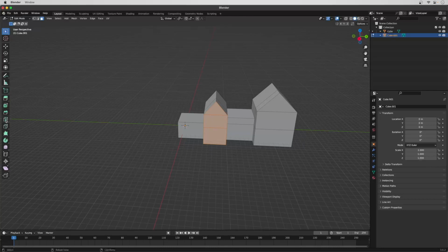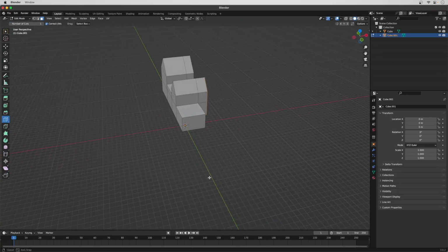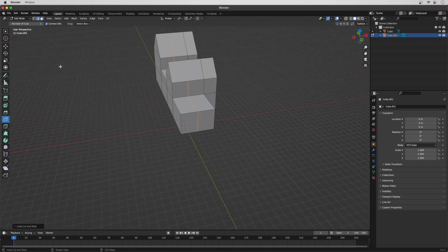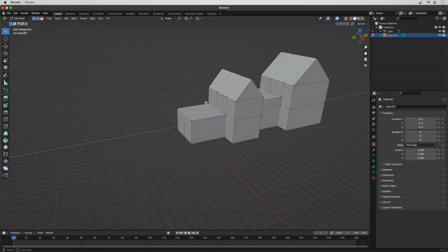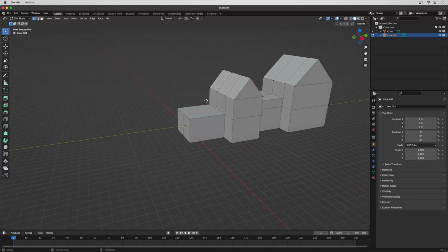Now we're missing half of our roof. So I'm going to go to the loop cuts and put a loop cut there. I'll go to the vertex select and my mouse select, and I'm going to select these 2 vertex. And I'm going to extrude it by 2.5 on the Z axis, so Z. And I'm going to select the edge here. Now X.